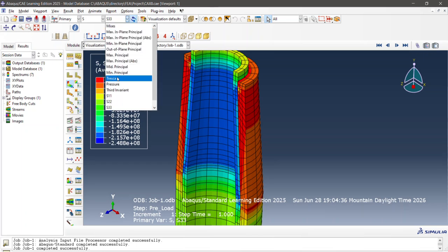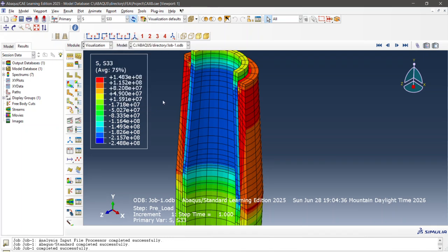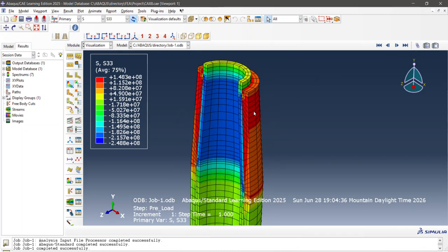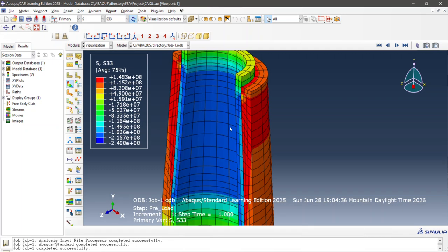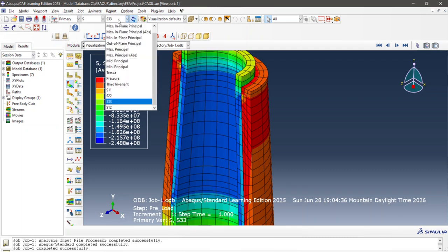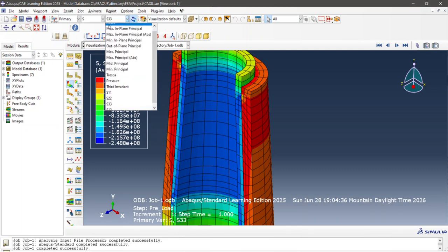And I would anticipate that not using the same material and same dimensions, you're going to see slightly different behavior, right? That makes sense. So your hoop stress, still seeing the same behavior, right? You're getting tension in your hub and you're getting compression in your mast. And that's going to be present throughout the flight of the aircraft, no matter what mechanical stresses it's going to be imparting. You're going to see very similar behavior in this interaction, in this coupling. And it's super cool to see.